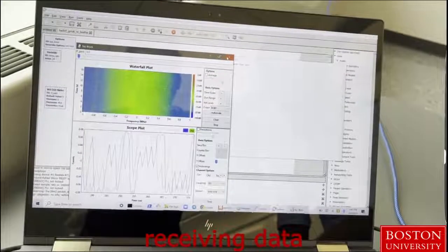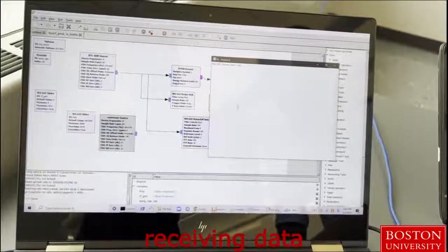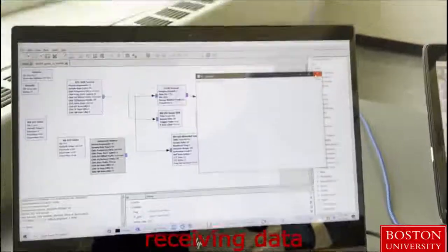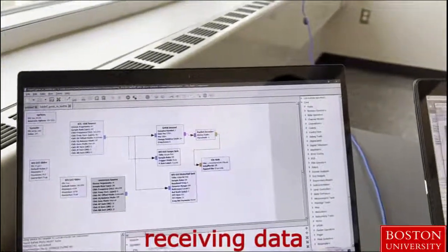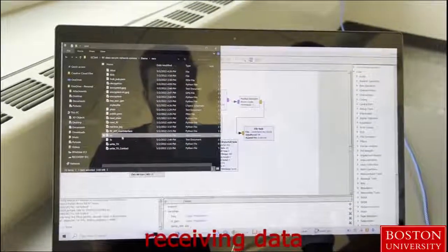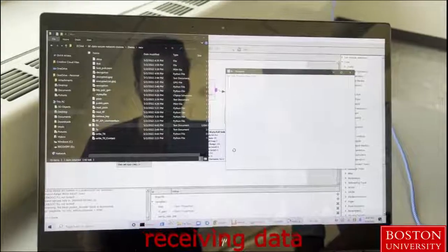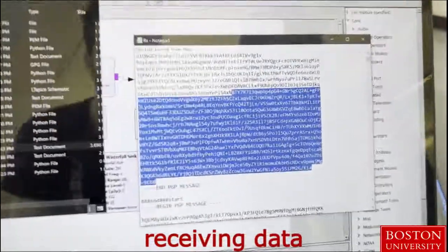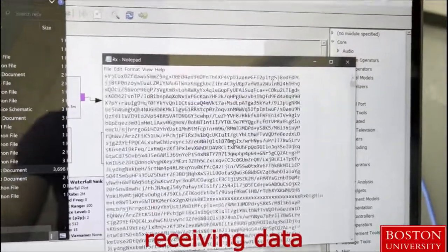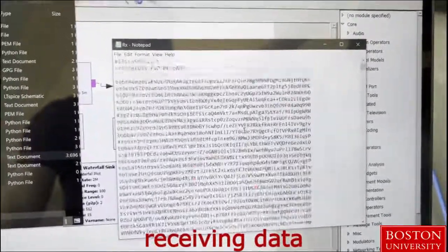The receiver then begins to monitor the RF channel as per our GNU Radio specification, receiving data over the air and populating an RX file with the message, which is encoded at a pre-agreed frequency. So with the use of threading, the monitoring stops once the RX file has been populated at least once, so likely much more than that. Here you can see the received message.